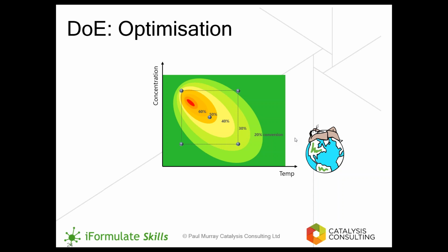So if we work one variable at a time, you carry out 11 experiments, you have 11 experiments worth of results. If you use experimental design rather than one variable at a time, we have the results from, in this case, a similar number of experiments, 9 with some replication will bring us back to 11, but we can predict the outcome of thousands of results. So any combination of these factors could be predicted what the outcome will be. And this will tell us where we want to operate our process. So experimental design is not really about working harder, it's about working smarter.